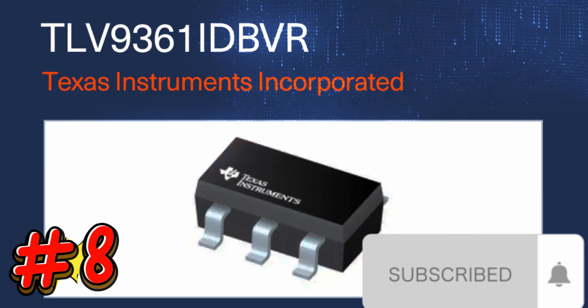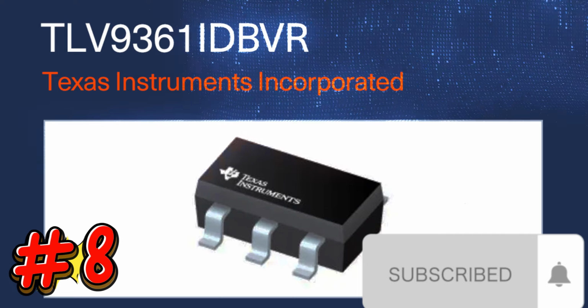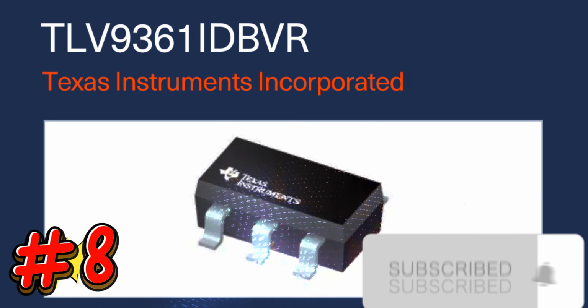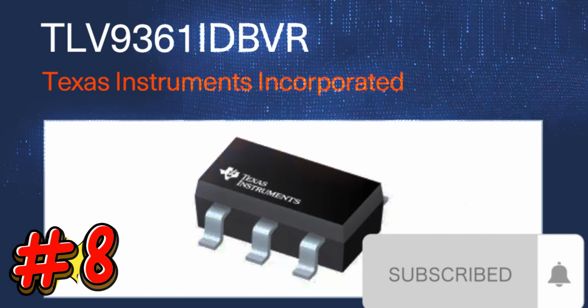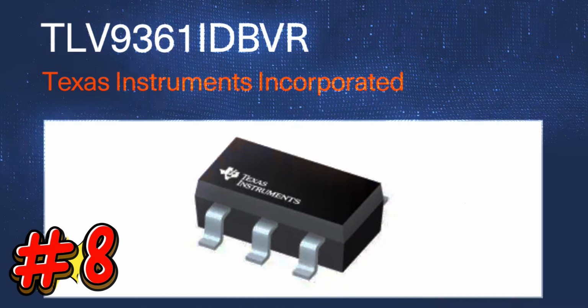It has an HBM ESD classification level of 2A and a CDM ESD classification level of C6 under AEC-Q100.